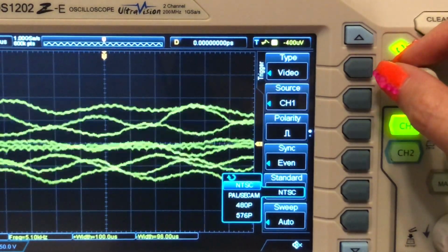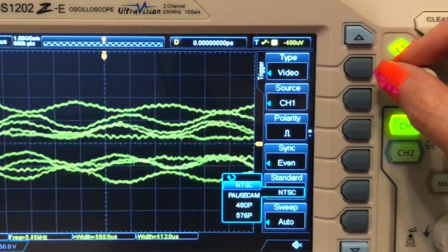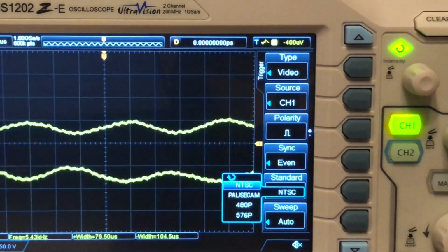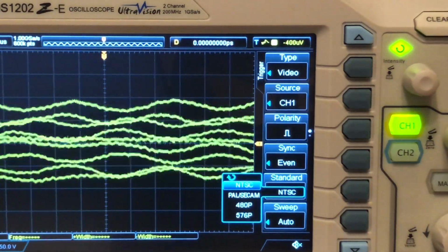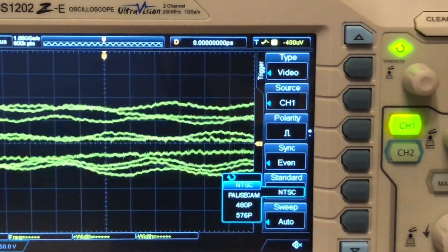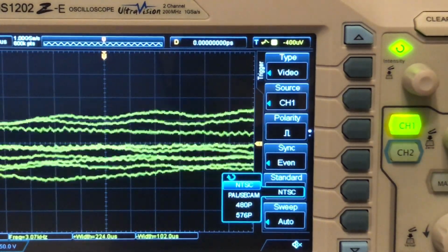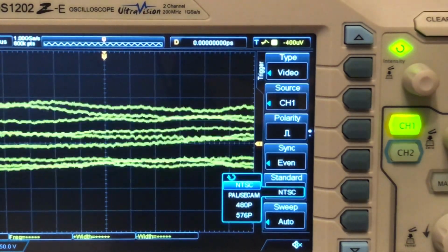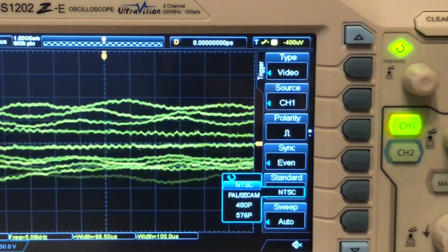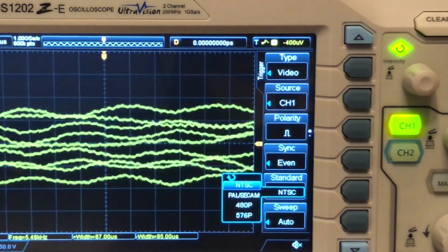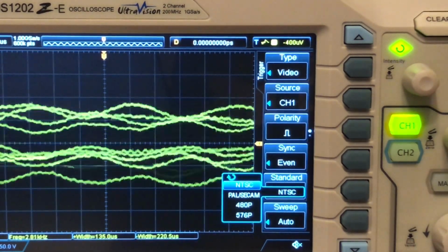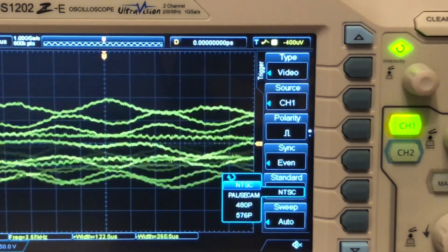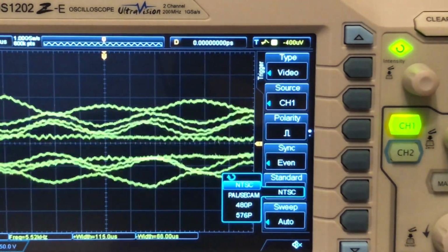It says PAL, SECAM. PAL: the frame frequency is 25 frames per second. The TV scan line is 625, with the odd field going first and the even field following behind. SECAM: the frame frequency is 25 frames per second. The TV scan line is 625 with interlaced scan.